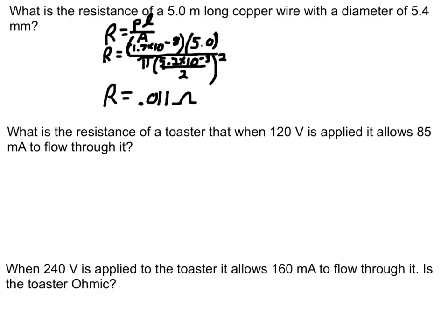This is why copper wires are so good. You should have a very low resistance in your wire to where it can pretty much be neglected compared to everything else in the circuit, which are lots of times in kilo ohms, for example. Remember, here's my area, here's the resistivity, entire area, pi. This was the radius squared. Here's the length. All right, so next problem that we're going to solve now.